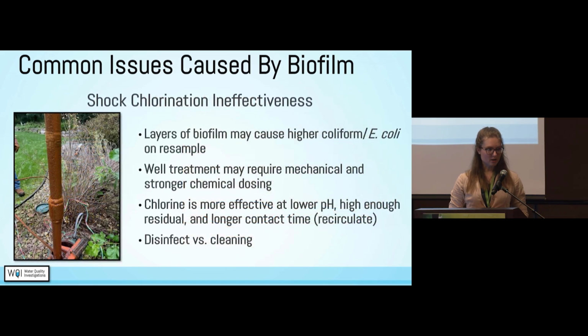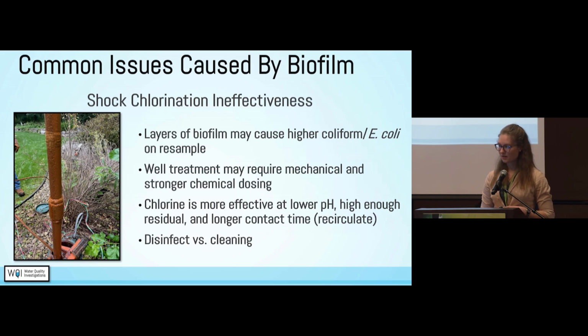Biofilm can lead to shock chlorination ineffectiveness. We've had cases where residents come to us and they have shock chlorinated their well 5 or more times and they are still coliform positive. That's because there is a layering effect of the biofilm in the well.